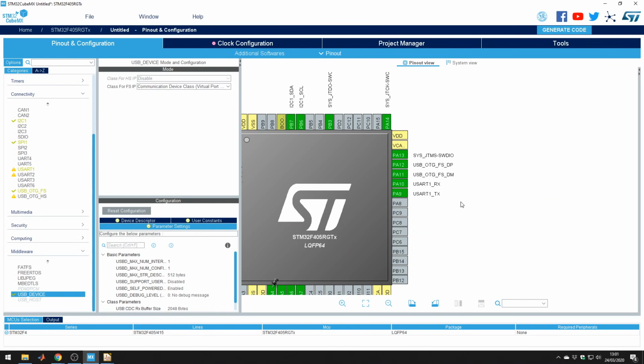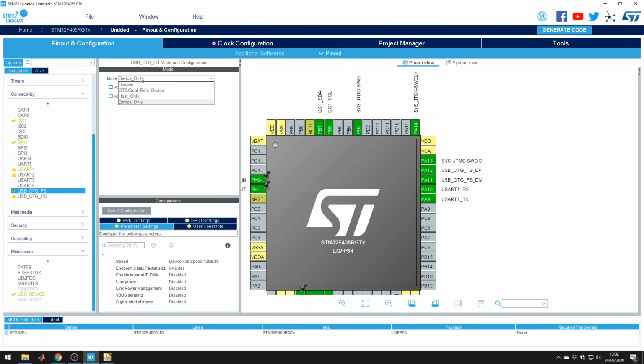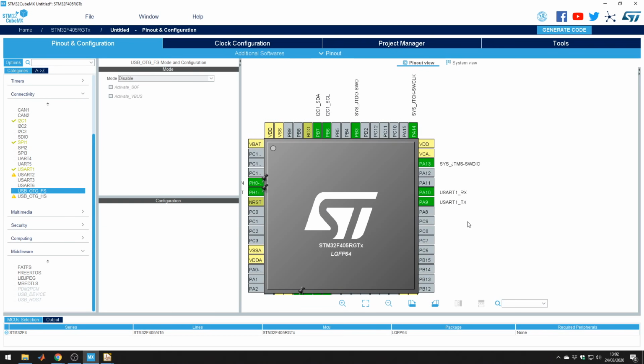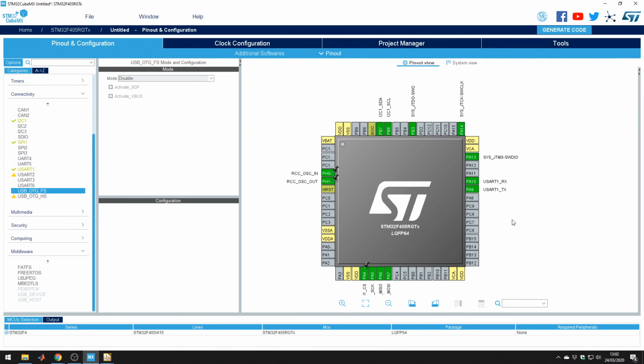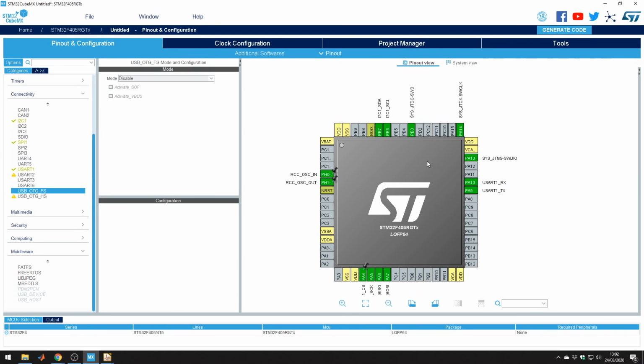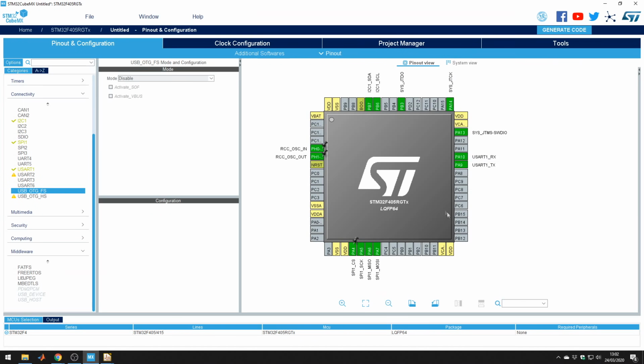If you want to save an extra chip, which can be an extra cost, of course, if you do this in volume, just use the USB and use virtual COM port. But for simplicity for this one, I won't be doing that, because then you have to route differential lines with a USB connection, and for the sake of this video, I'll just keep it short. Okay, but our connections are I2C, SPI, and one UART.